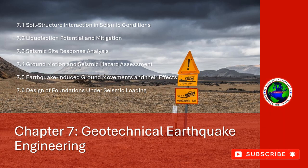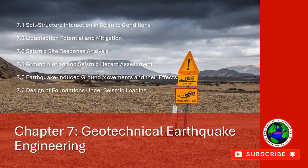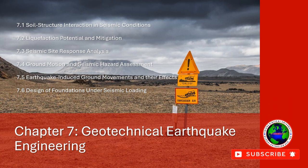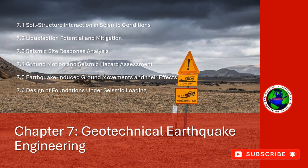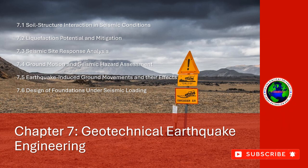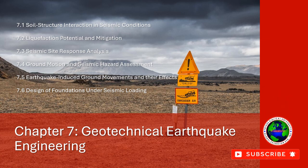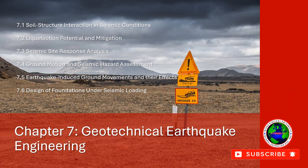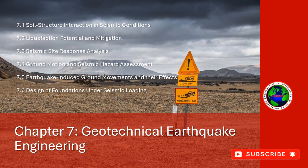4. Surface rupture and fault displacement analysis. Surface rupture analysis helps identify active fault lines and assess the risk of fault displacement during an earthquake. Geophysical surveys, fault trace mapping, and historical earthquake data are used to predict potential surface rupture zones. In areas of high risk, avoidance or reinforcement of structures crossing fault zones is recommended.